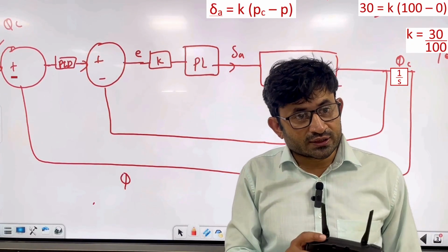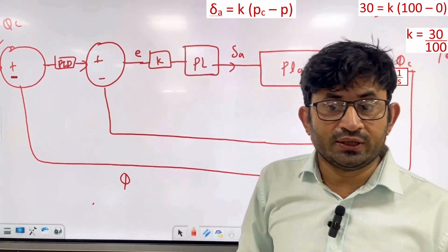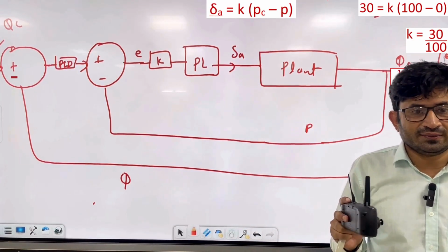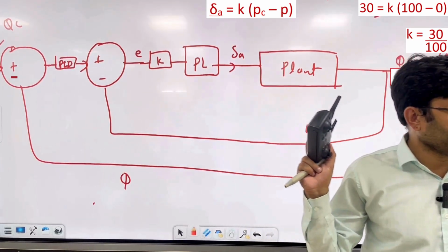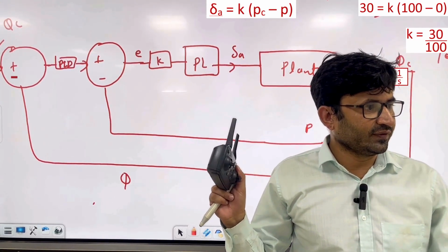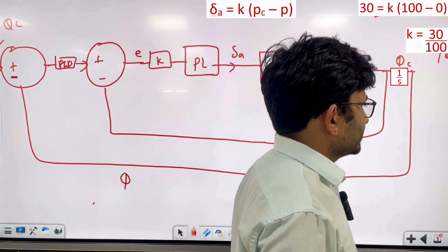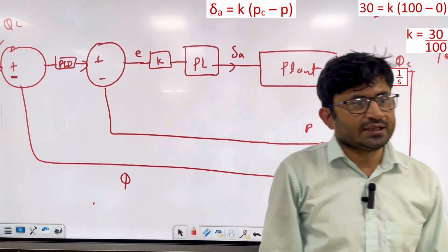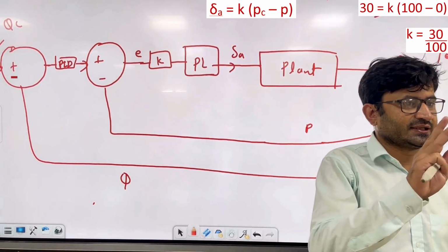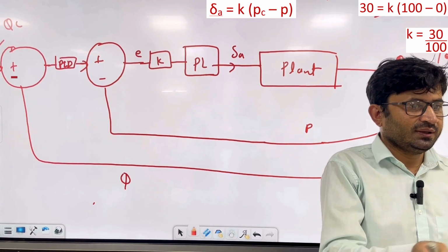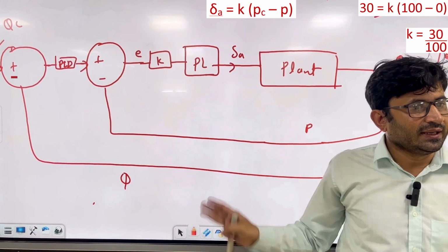So in stabilization mode, only roll and pitch are set in an automated manner. It will become level flight when you release the stick. That is called stabilization mode.